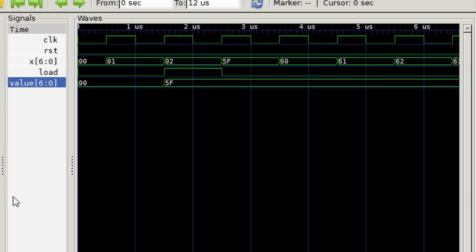All right, so we can see that there is actually 1 clock edge before the process actually starts. Because signals by default get reset with zeros, X is 0. So on the positive edge, we get 1.